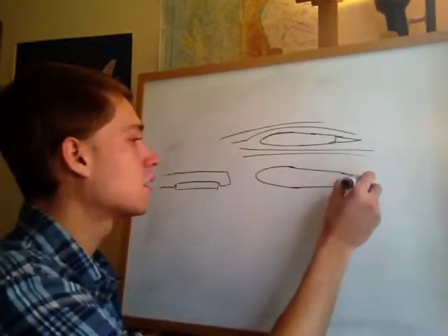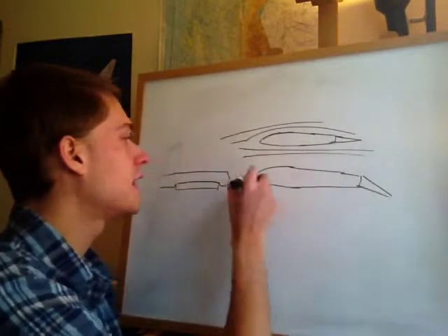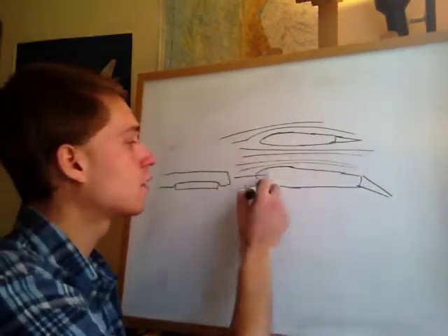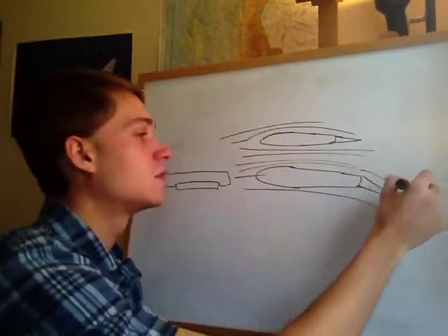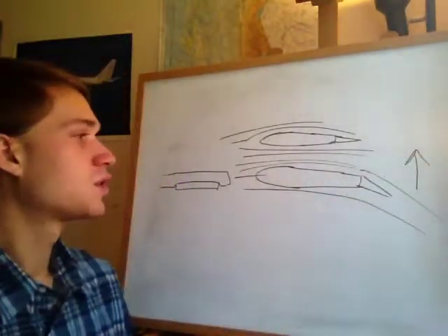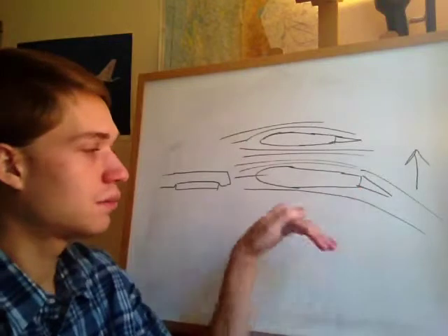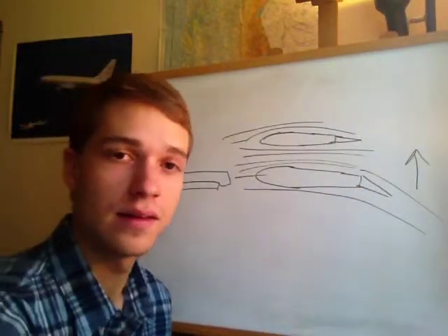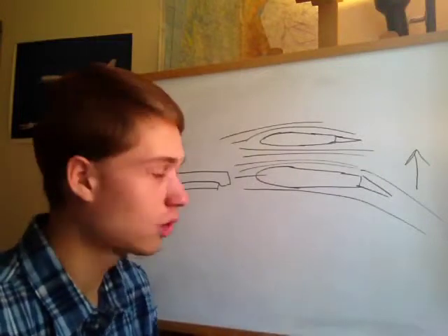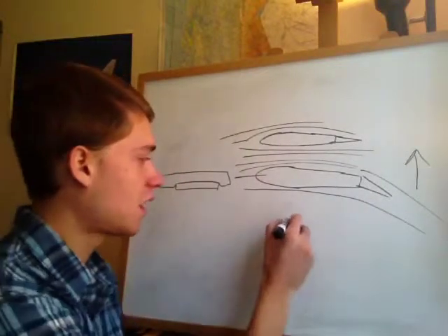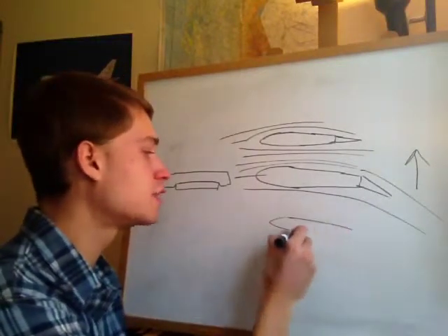Okay, so let's take a look here. We've pointed the aileron downwards. Now the air is flowing over, and it gets deflected down more, and you're producing more lift. So when you have the aileron pointing downwards, that part of the airplane is going to want to rise up because you're producing more lift on that side. The opposite is true if you raise the aileron.